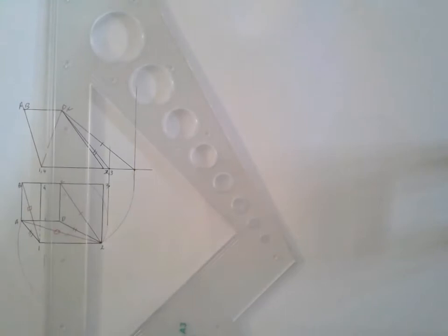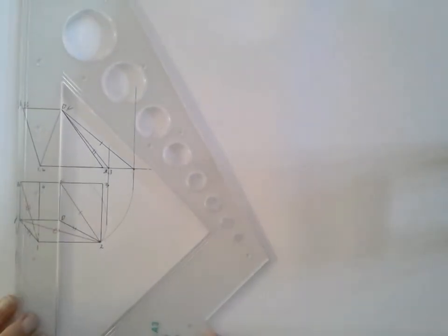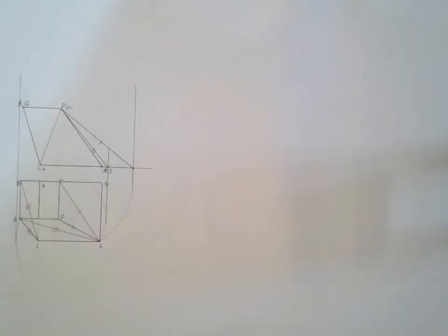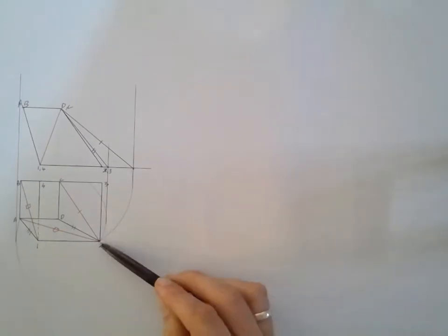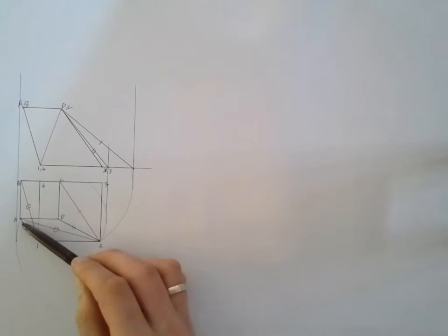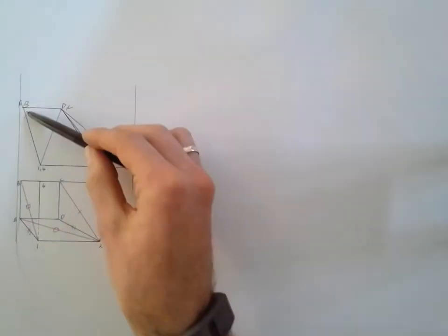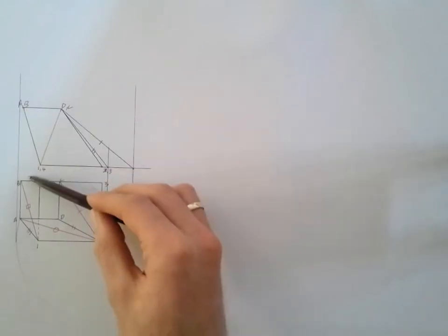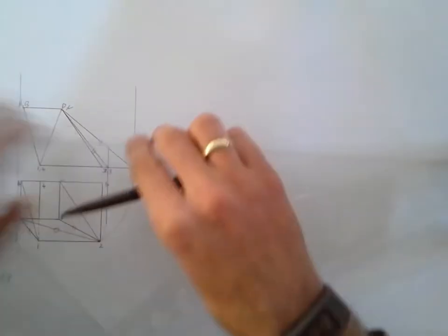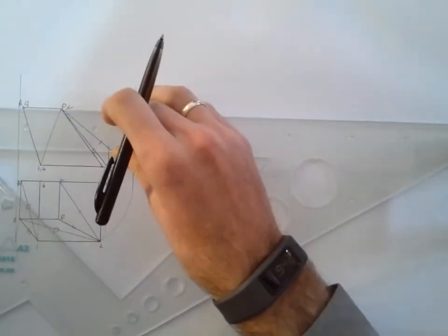And I'm going to take the edge of that arc, project it up into my front view, and now you need to remember that you've now changed points, the point that you're projecting. Instead of projecting a base point, you are now projecting a top point. And because you projected a top point, that projection line now has to be joined up to the top part of your front view, not to the base. So I'm going to extend the top of my front view,